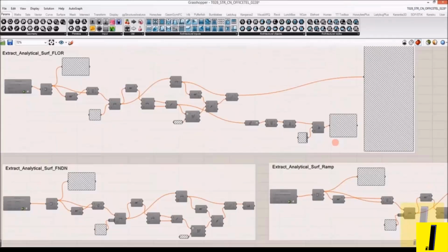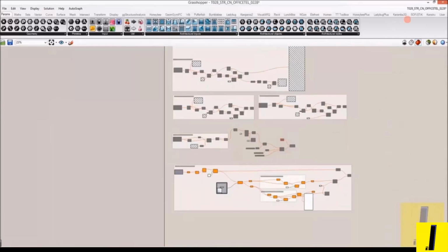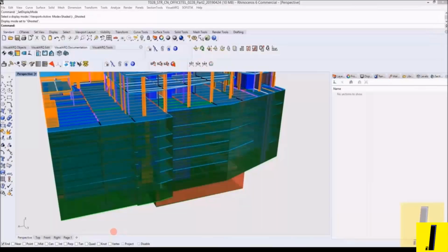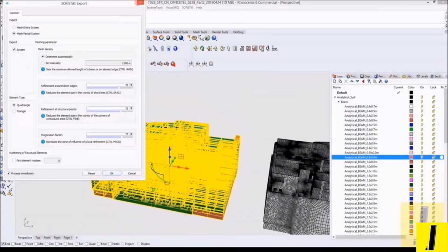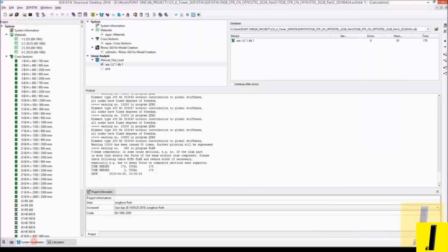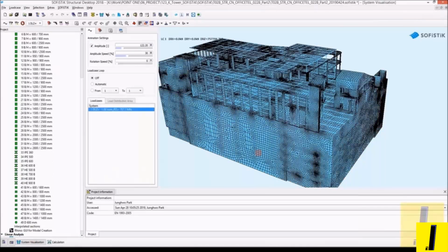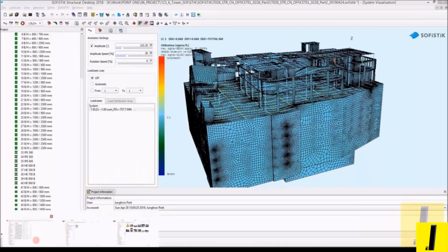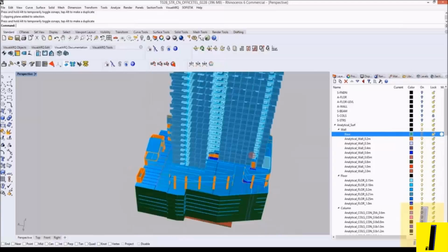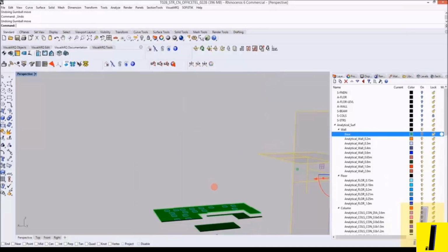It's just standard Grasshopper, but we could define all the building components to convert to the analytical model. The result here is, obviously, not every analytical model came from the Grasshopper output. I had to manually adjust in Rhino, but it's still really fast and efficient to work in Rhino rather than Autodesk Revit for this case, because there's not much constraint for the analytical model.